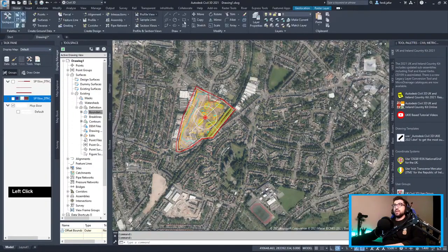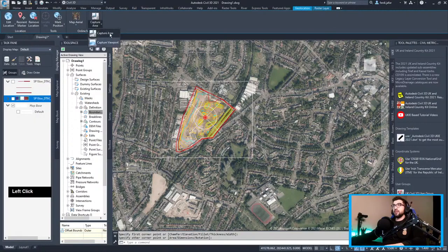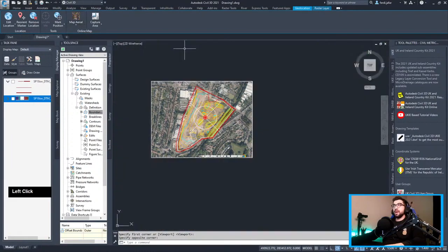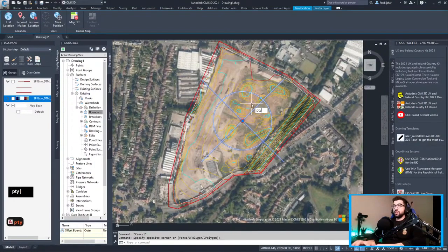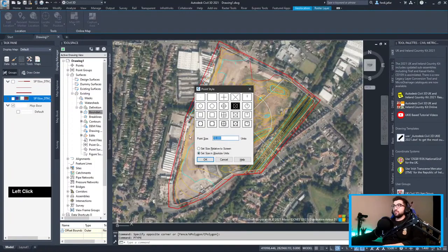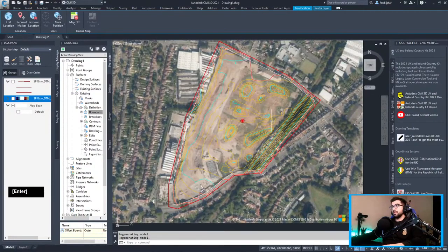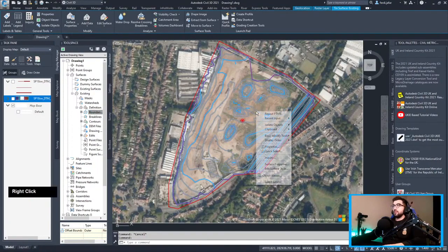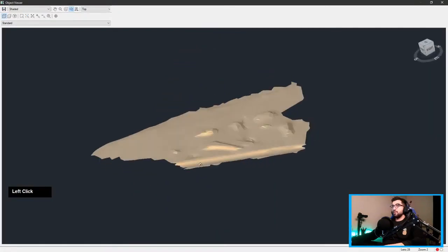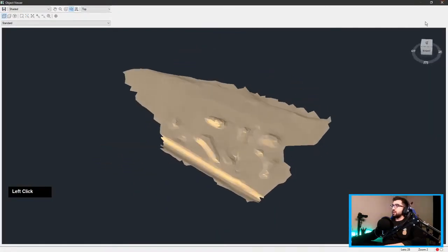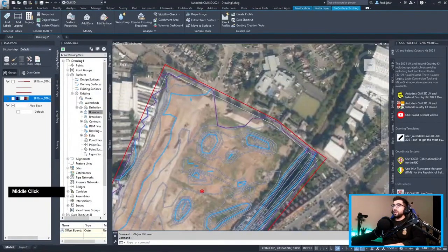And now as well, we're gonna draw a rectangle just so we can have the site and the geolocation capture area. So do the same one here, and then just turn off the map, and there you have it. Let's delete our point. We don't actually keep the point, just change the point type from relative to screen to absolute units and change it to 1 so it won't be visible. And then we can right click, object viewer, and that is our site that we have imported. Now, I'm not sure why they cut it off, but let us review.